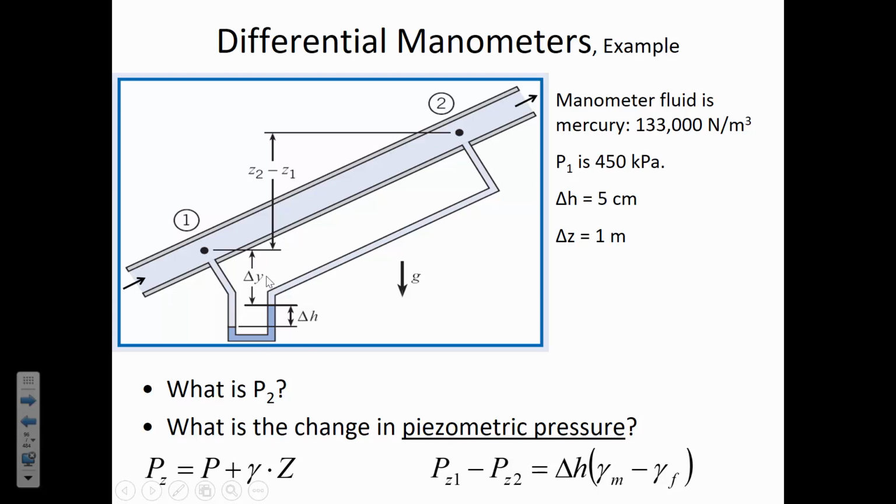Now, we can see from this differential manometer a deflection. And in this case, that deflection is only accounting for the pressure difference that's due to pipe friction. If we stopped the flow through the pipe, think about now, it shows the arrows indicating fluid flow, but if we closed a valve and now there's no water flowing through the system, then delta H inside that differential manometer would cease to exist.